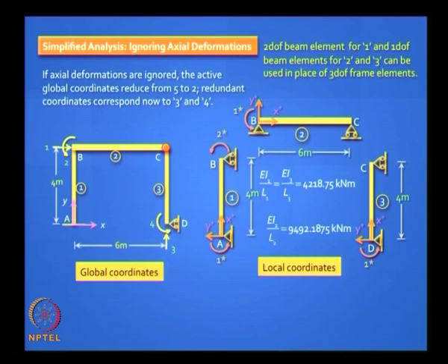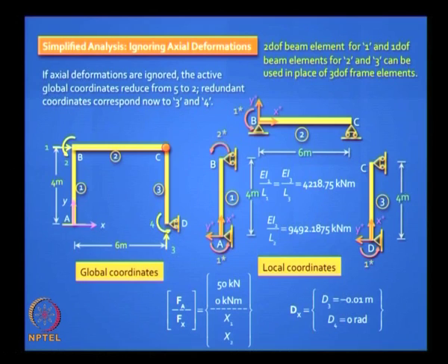For element 1 you still have 2 degrees of freedom, but because we want to take advantage of the internal hinge at C, I put a roller support there, so I have only 1 degree of freedom, and my FA and FX vectors are easy to calculate, it is smaller, much easier to work out. Dx is the same, only thing is earlier we wrote D6, D7, now we write D3, D4.